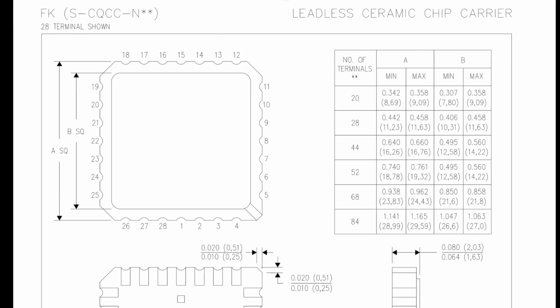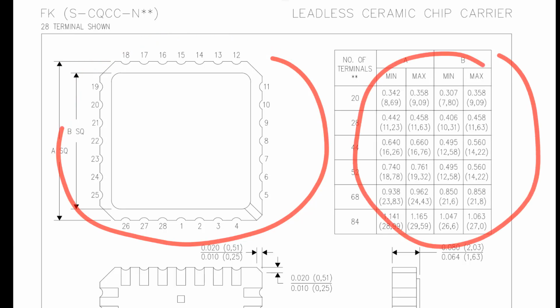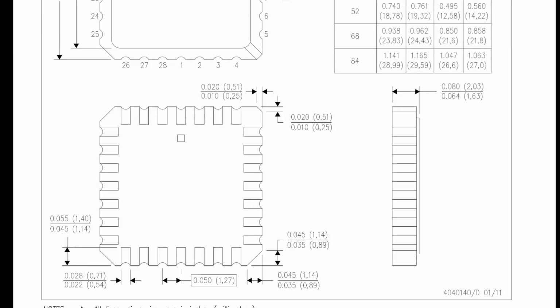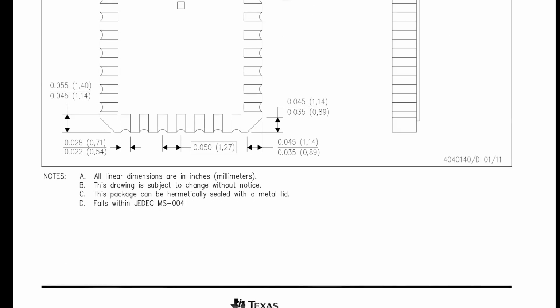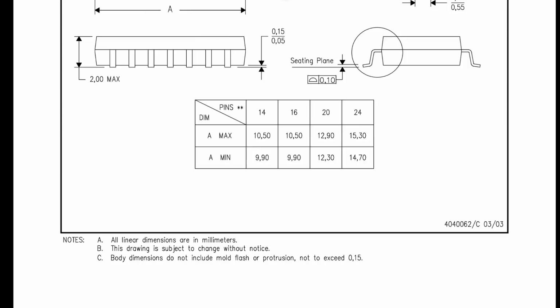And now we have our physical package requirements. These are the min-max. These are if all your mechanical engineers are getting a bit moist now about the package. And there's the leadless chip carrier. So how that's designed matters if you were designing a pad, for example, and your pad went around there like that, then this sort of drawing matters, right? So let's go down here.